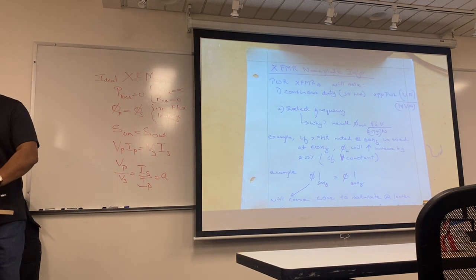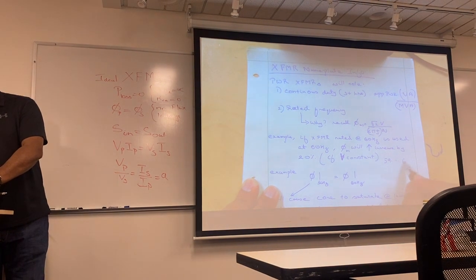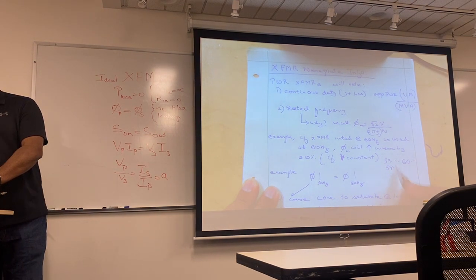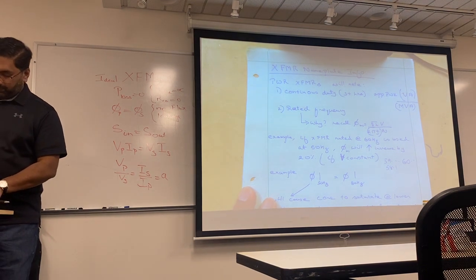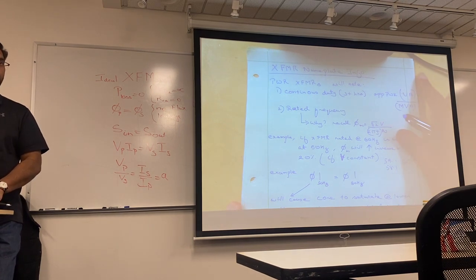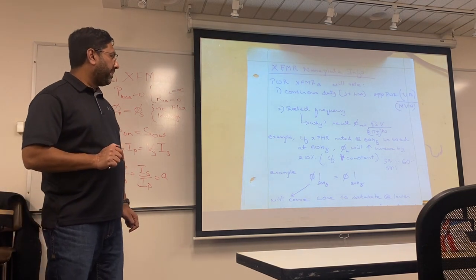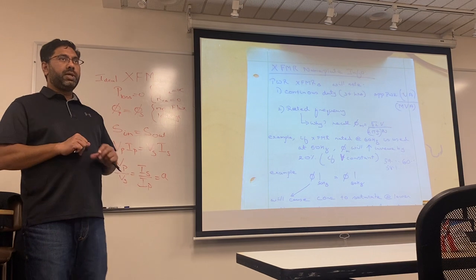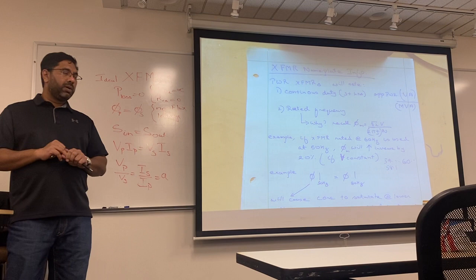In fact, we are so paranoid about this frequency, 59 point something is good enough and 60 point something is good enough. If I see like a 58.1, we would rather shut down the grid and restart the grid. Interesting. It would just damage everything if it's left too long, that wrong frequency. Frequency is one thing that we just don't fool around. Yes, it will damage a lot of equipment.